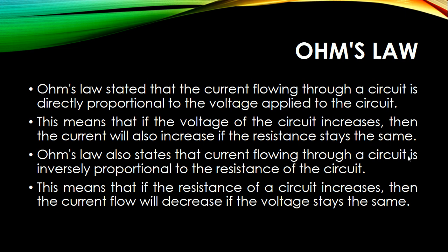Okay, since we've already discussed the current, the voltage, and the resistance, it's related to Ohm's law. Ohm's law states that the current flowing through a circuit is directly proportional to the voltage applied to the circuit. This means that if the voltage increases, then the current will also increase if the resistance stays the same. Ohm's law also states that current is inversely proportional to the resistance of the circuit. This means that if the resistance increases, then the current flow will decrease, as long as the voltage stays the same.